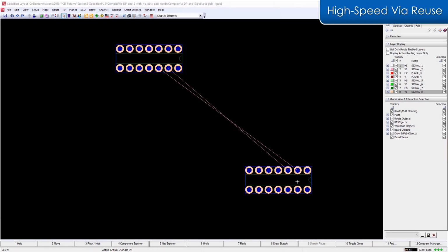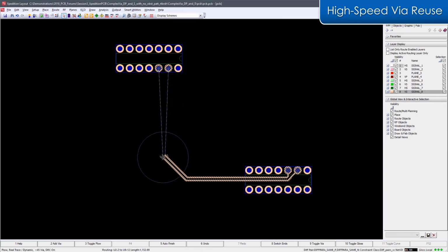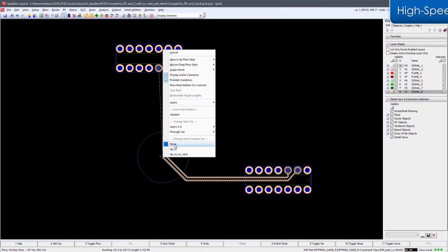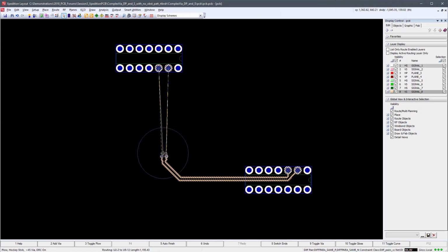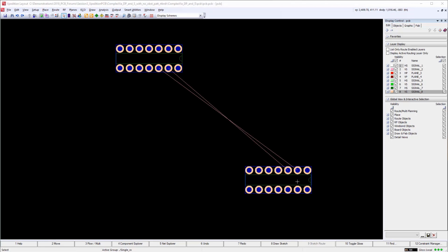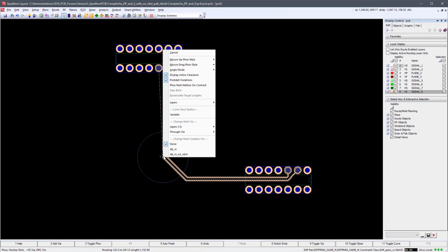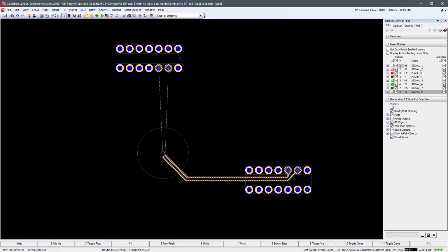For teams working with high-speed designs, there are times when new routing techniques are required. One of those is complex via structures. These are via models that are user-defined and used for high-speed routing, layer transitions, and stitching vias. Many times, these complex via structures are defined by analysis using 3D solver tools like HyperLynx. In this example, we see a diff pair being routed using the normal diff pair via solution. It has been determined that a high-speed via structure using shielding vias and trace obstruct is required.